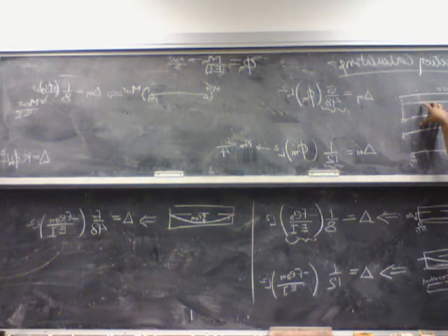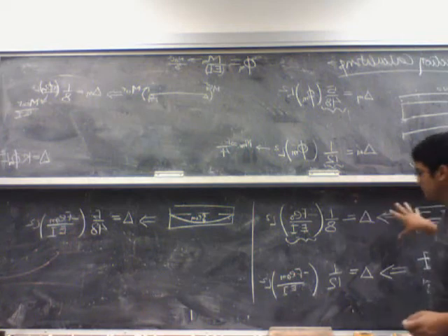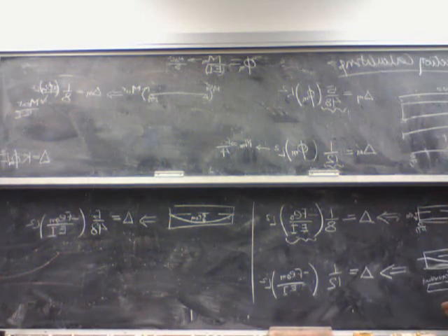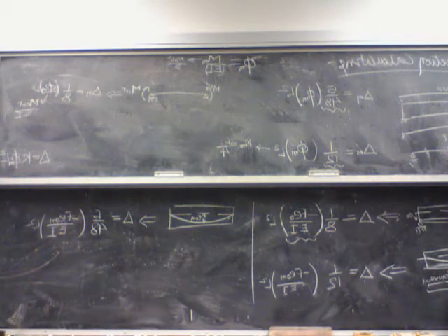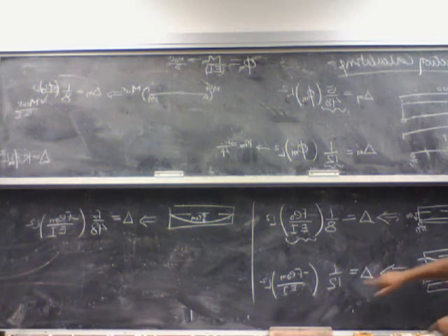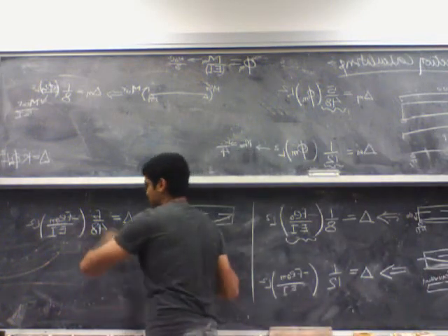If you break that apart, say like you drew the draped tendon with the straight line, you drew it back to the centroid, but we've seen a lot of them that are down. Yeah, okay, I'll actually do one of those. You see superposition. Yep, so you just simply use superposition. So these are the three cases for the tendon profiles. If you have constant eccentricity, you use this formula. If you have draped tendons and they both go back to 0 at the ends, then you use this. If you have a parabolic tendon, 0 at the ends, you use this.